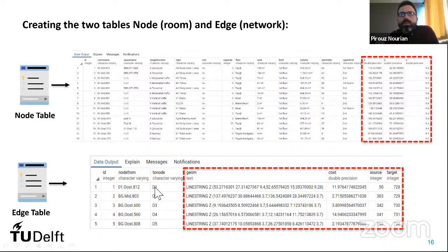This has come directly from Revit, because during the creation of the 3D model, if you give the first door a name like D1, Revit will continue to give it a number D2, D3, D4, D5. So I will have all the semantics for the doors ready for me.